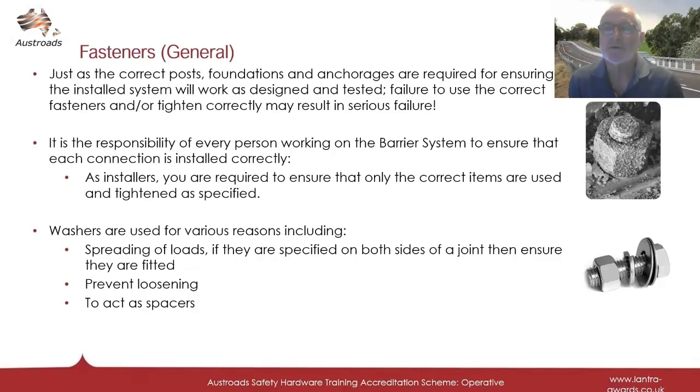As installers, you are required to ensure that only the correct items are used and tightened as specified. If washers are specified, they are used for various reasons, including spreading of loads. If they are specified on both sides of the joint, then ensure they are fitted. They prevent loosening and can act as spacers.